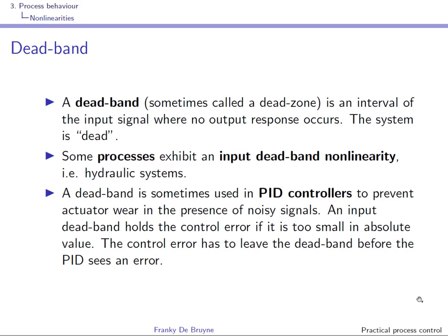A deadband or dead zone is an interval of the input signal where the output is not reacting, so we're saying that the system is dead in this input interval. It is typically a nonlinearity that you'll find at the input, and some processes will exhibit this input deadband nonlinearity.